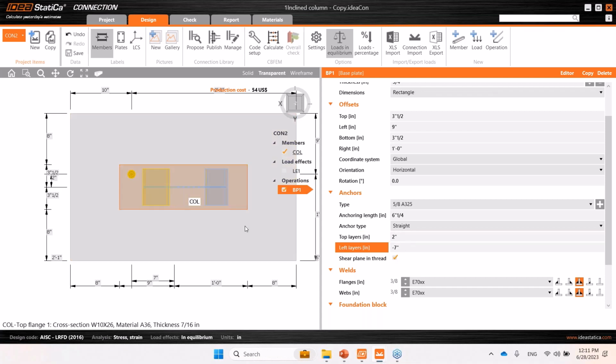And then I want another bolt here, so I'll use the top layer input. I'll place a spacing from that last bolt. You can see I am using positive, but I want that anchor over here, so I use a negative value. Okay, and then for the left layer, this coordinate will be -1, 4. Oops, that will be positive then. There you go. So again, this is an easy way to locate coordinates from the node.